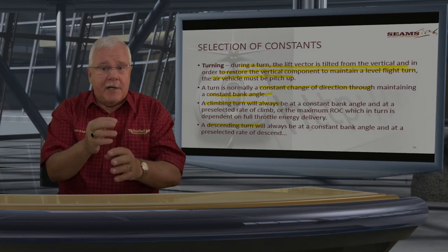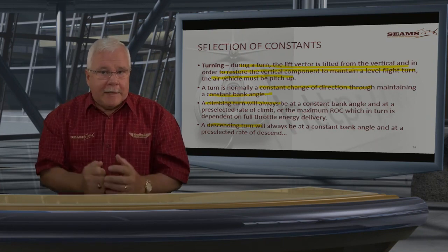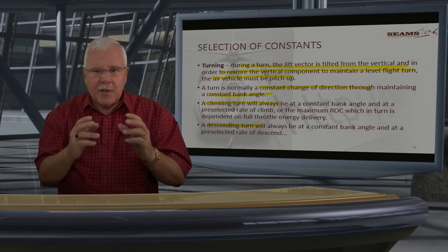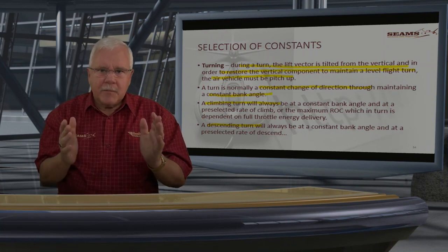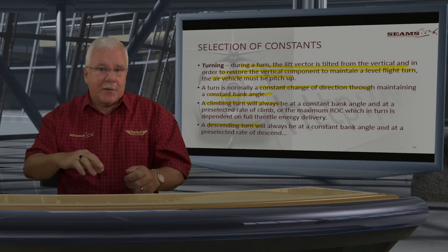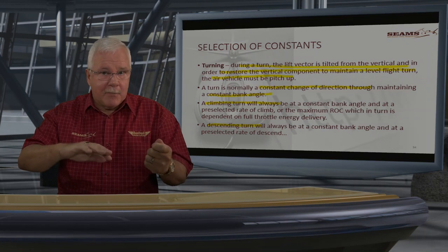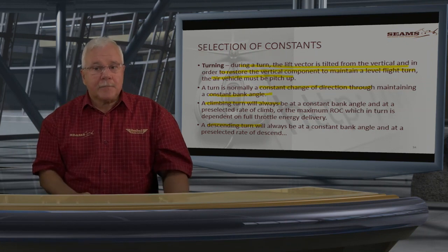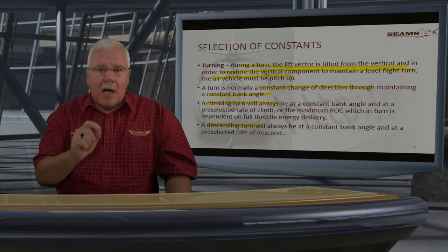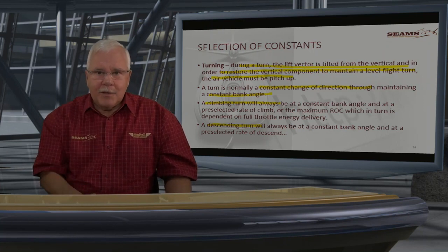All right? And the speed, well, normally in normal turns, there's going to be a little bit of a loss of speed. We don't do much about that. But remember, when you do a steep turn and the speed reduces, it might actually mean that you'll have to increase the power, to climbing power, to maintain the speed. Always keeping autorotation in mind.